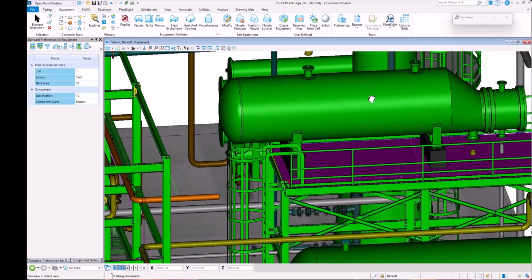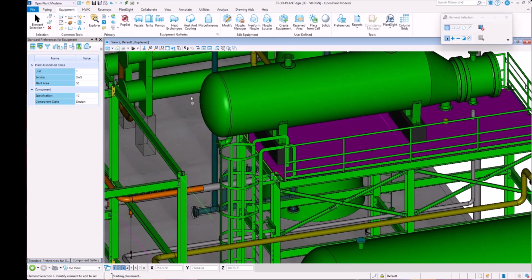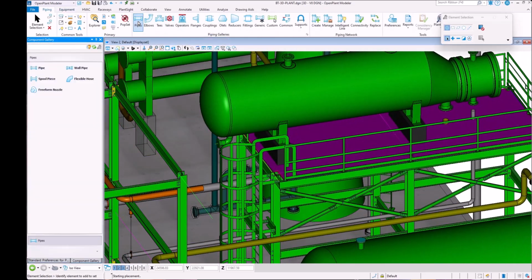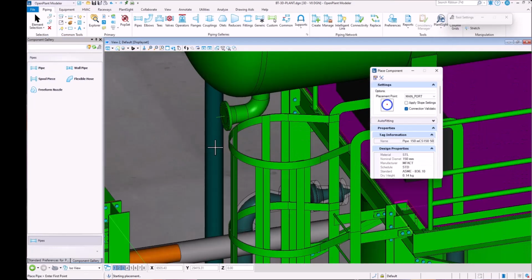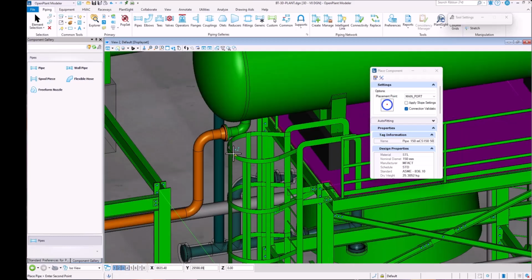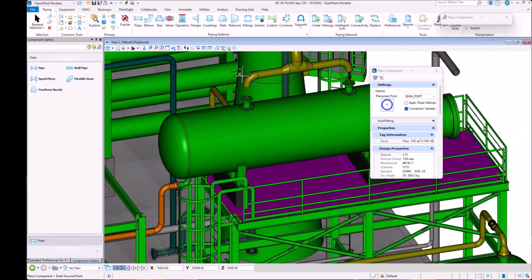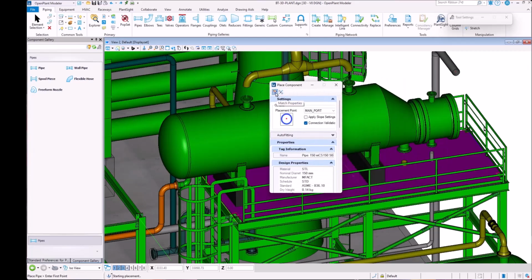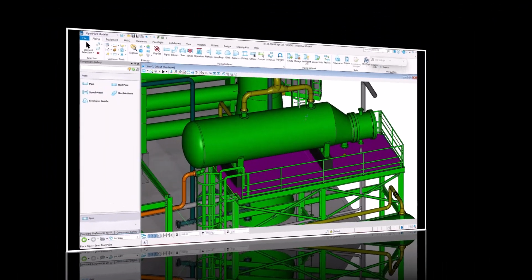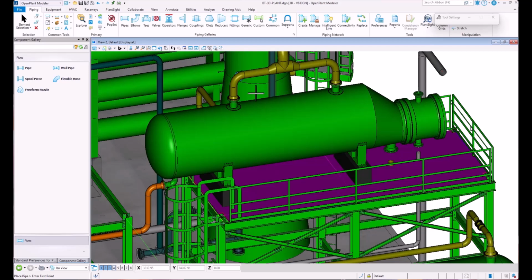Now, let's reconnect it to the piping circuits by creating the bends and straight pipes that correspond. In the Piping tab, we can select the types we need. You can see how intuitive the process is. Inlet nozzles located at the top of our vessel also need to be connected, following the same simple procedure. Now we can see the final rendering of our imported vessel, perfectly connected to the piping system of the rest of the plant.